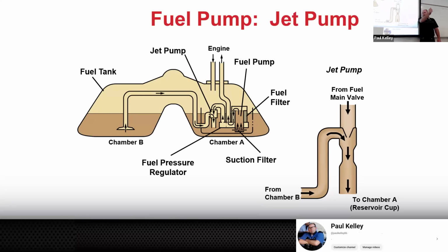So they do make special little brushes to clean the tank all up, right? You could slam a fuel pump in there, something I've done many times, but if you still have small particulate and debris in the tank, how do you think your new fuel pump's going to like that? Probably not going to be real happy pulling particles through the high-speed fuel pump and motor, right?